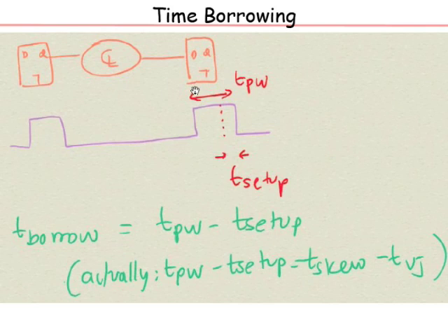But when you actually lay out the design, you finish your layout, at that time the wiring lengths can be a little long, etc. Things are not exactly the delays, because you don't know the exact delays when you're doing schematic, because you don't know the wire lengths, you don't know the capacitance. Only when you do the final layout do you know the situation. And now when that happens, it can happen that the delay out here is slightly more than the clock period. Of course, if it is very much larger than the clock period, you just have to go back and redo your layout or redo your design.